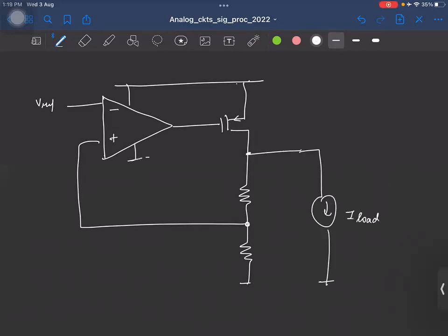So now again, this is also a good regulator because if this varies, the op amp is forcing this voltage V out by K to be Vref. So any variations here ideally will not get reflected at this point. Okay? And the second problem we had was the load current. Now the load current is flowing here and the op amp can just draw the bias current required so that it operates in the required fashion. That's all. Okay. So let's stop here and we'll continue next.